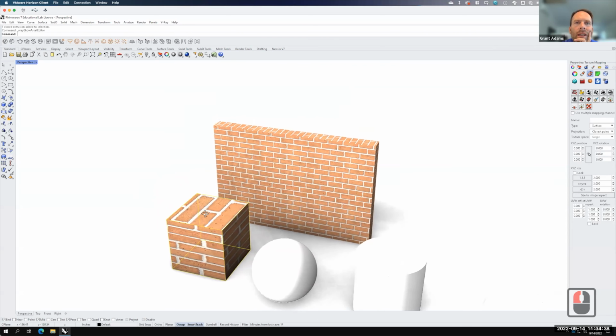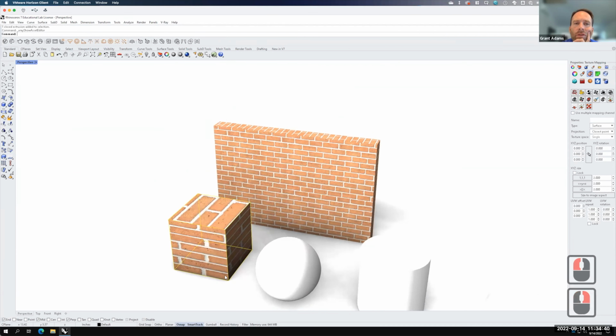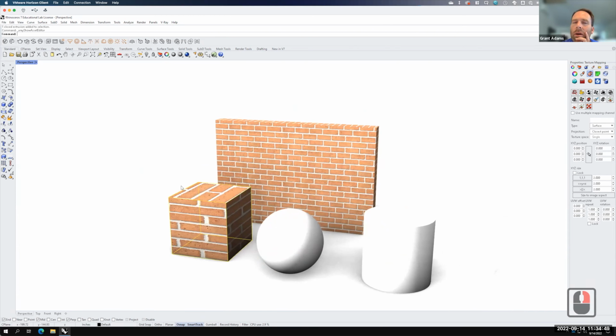There it is. Now this is 4 feet by 4 feet by 4 feet. So it's a different layout. So it doesn't look quite as bad. It's a little stretched, but we still want to apply a new texture map to it. So with it selected, we'll choose the box mapping. Again, we'll come up here and say, let's use a bounding box. We use world. And now we have, capped, yes. And now we have our texture applied.